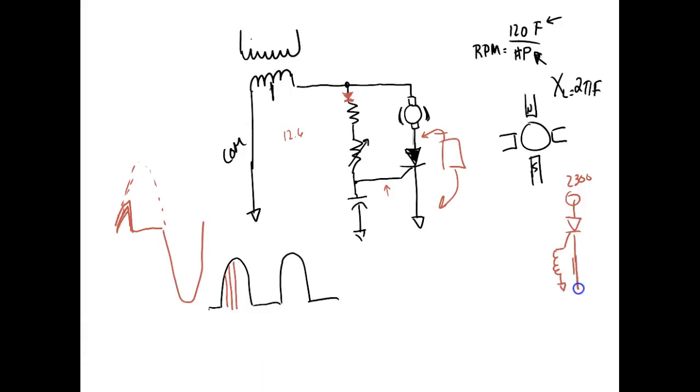On the cathode side, they'll bring another wire over like that, so it won't be a common. Then we'll have our transformer over here, and this right here will go back to our electronic firing circuit. That makes sense? And then we'll take this AC and run it through a transformer that steps way down. This allows the electronics to be in sync with the voltage going to the SCR. Does that make sense?